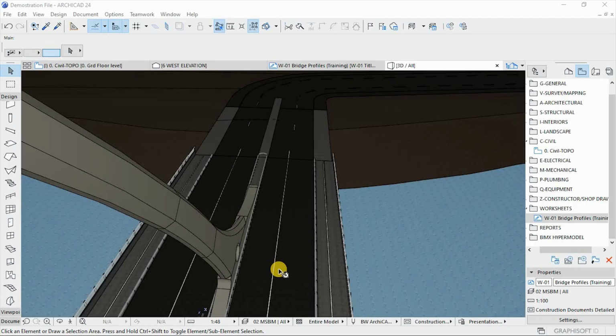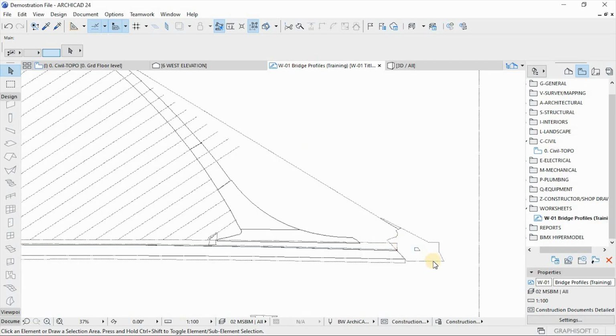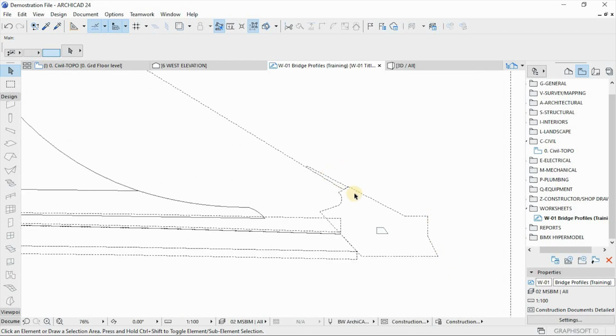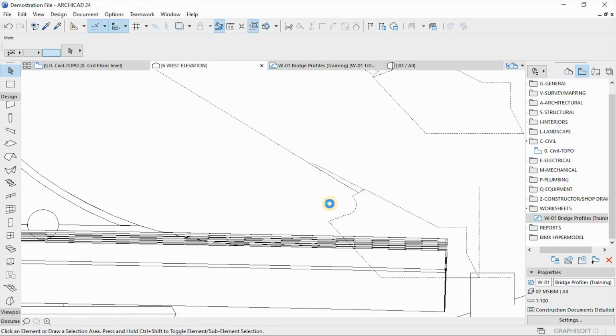Let's start by creating the two suspension clamps that will be fixed here, and then the other one will be located here. So I'll open the profiles view, and then these are the suspension clamps profiles. So what I'll do, I'll copy this and paste it on the elevation. We're going to use Move Tool to create this. So elevation is the perfect view for that. So if you open the elevations, I already placed the profiles here.